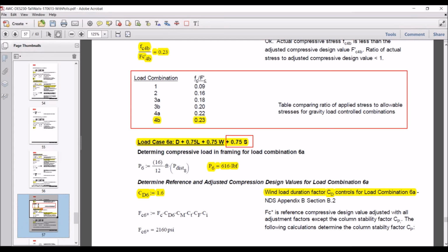And some designers will say, well, why can't I just take those load combinations and divide by the load duration factor, kind of divide it out, and guess, approach it that way? Well, again, it's because we don't apply that load duration factor to E, to modulus of elasticity. So when we're looking at buckling critical applications where you're going to include E in the analysis, that just would not work. So it's one of the things that we were excited about teaching in this webinar, this influence of load duration on these various load combinations.